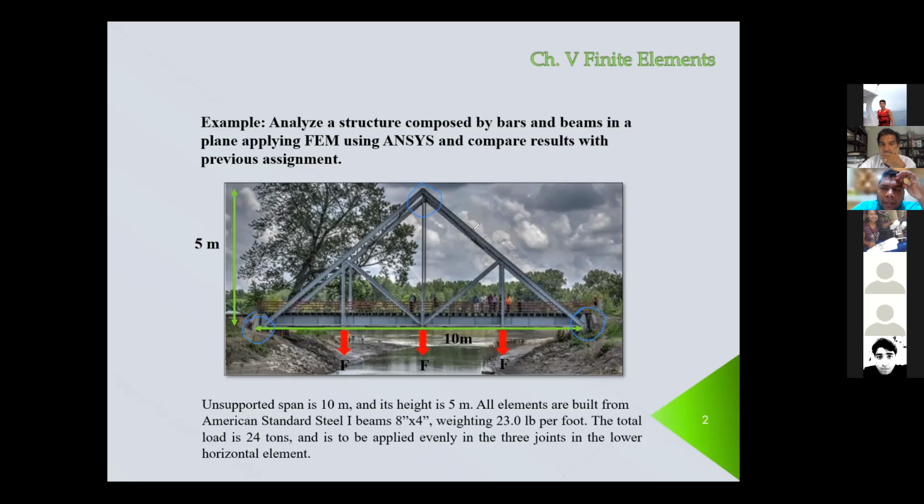I don't put any boundary condition there, because I would analyze the whole structure, not part of the structure. If I analyzed half of the structure, I would have to put a certain boundary condition in the middle.